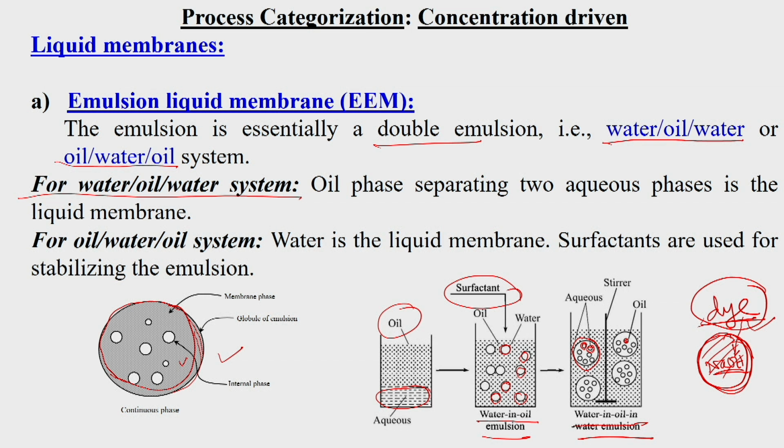So, all these emulsions will fall down in the liquid emulsion system, and then they will be collected from the bottom of the container. But one point is that it has a limit. Once it exceeds its limit, the emulsions will be broken, or many emulsions will coalesce and the size will become larger, and sometimes they will also break. Due to the reaction of some amount of sodium hydroxide with the oil also, the stability of this film decreases.